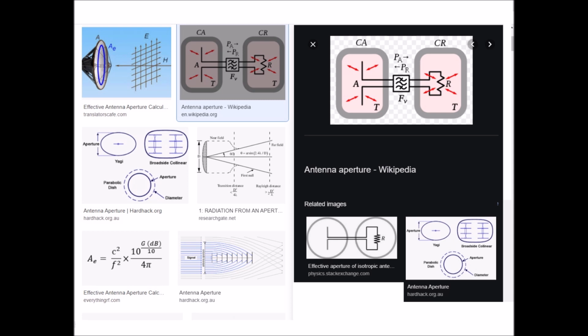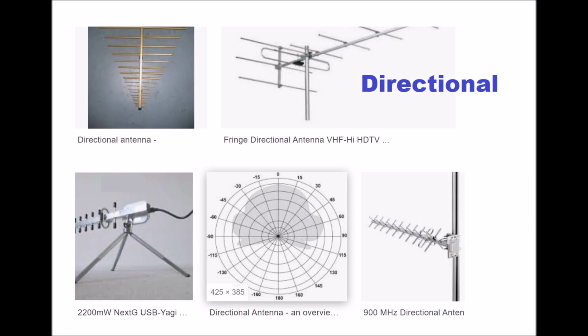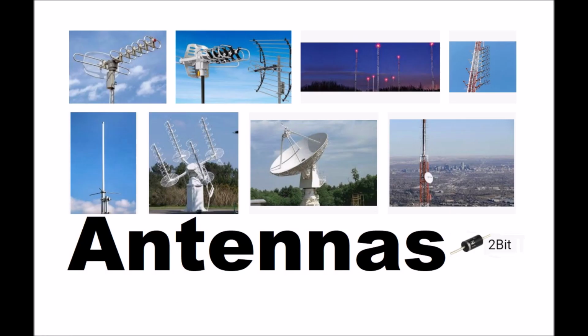The refractor alters the spatial characteristics of the wave on one side relative to the other side. It can, for instance, bring the wave to a focus or alter the wave front in other ways, generally in order to maximize the directivity of the antenna design. This is the radio equivalent of an optical lens.